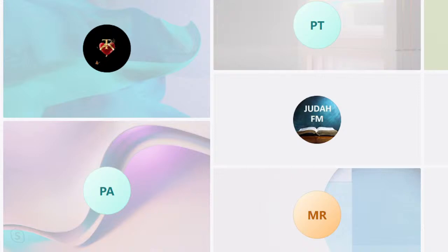These beams repeatedly sweep across the face of the monitor many times per second. So it's constantly redrawing the image that we see on the screen. And this redrawing of the image is known as the refresh rate. And the refresh rate is measured in hertz. So for example, if the refresh rate is 60 hertz, then that means that the beams sweep across the entire face of the monitor, redrawing the image at the rate of 60 times per second.